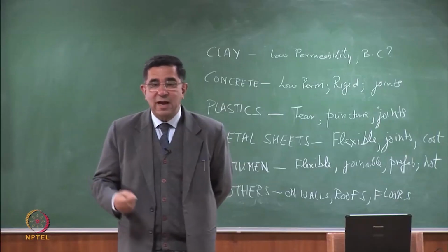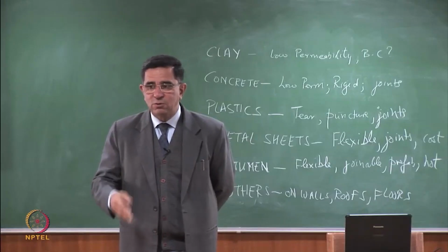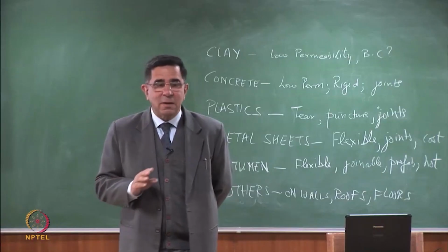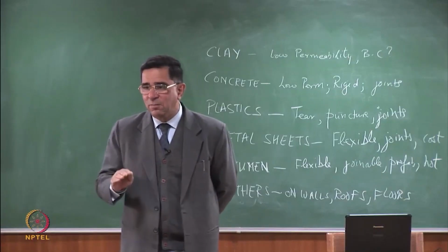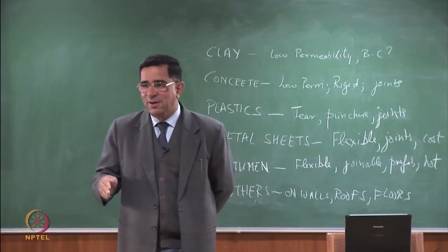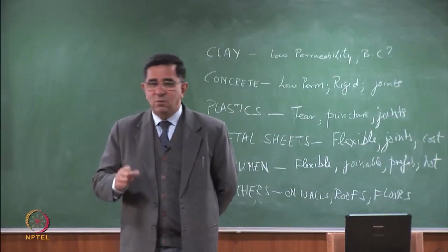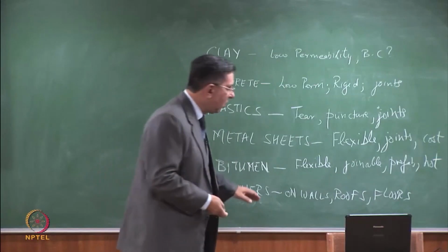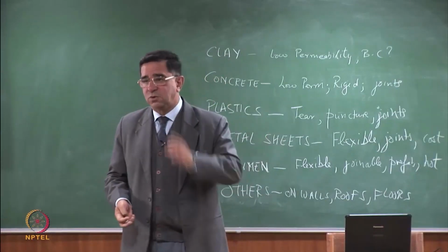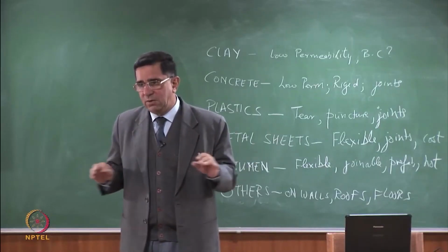What you are trying to say, I think, is that when you put the paintbrush on the soil, instead of the paint going to the soil, it may stick to the paintbrush. That's what you are trying to articulate. The substrate is not strong and uniform. So you can't paint anything on soil. The soil might want to paint itself onto the material that you are trying to apply. So you may not be able to transfer it to the soil. So all these things, which are these magical resins, polyurethanes and waterproofing compounds, they work well on walls and floors and roofs because the base is very strong and you can spread them very thin and very uniformly.